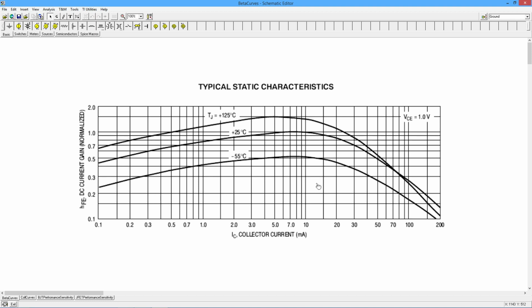So we need to remember that beta is not a fixed value. We very often go through computations and we say, oh, beta is 150 or beta is 125, or whatever it works out to, whatever we're going to use in that problem. And we forget that it is in fact a variable. We try to treat it like a constant. We try to design the circuit so that the value of beta is not supremely important, and the circuit is not very touchy to beta in its overall response, but we have to remember that there is a variation.